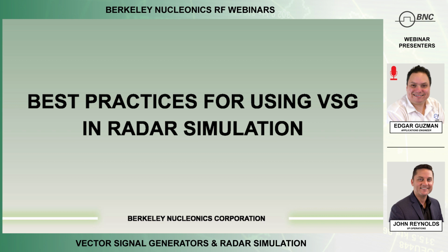Once you have your system simulated enough that you're confident it'll work how you want, you go to hardware in the loop, where you're able to test your simulation or your signals with actual real world communications from other systems.